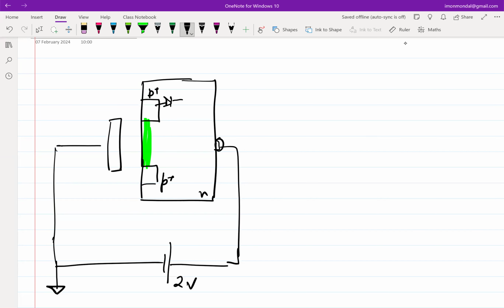So if that is the case, can you comment on what is the voltage that I would need on this P-type silicon or P-type doping in order to ensure that? Is there a limit on the voltage that you would want on the P plus tub or P plus island in order to ensure that the PN junction is reverse biased? Less than 2, right? It cannot be more than 2. In fact, regardless of whether I am talking about the P plus on the top or the P plus here, both the voltages have to be less than 2 volts, right?